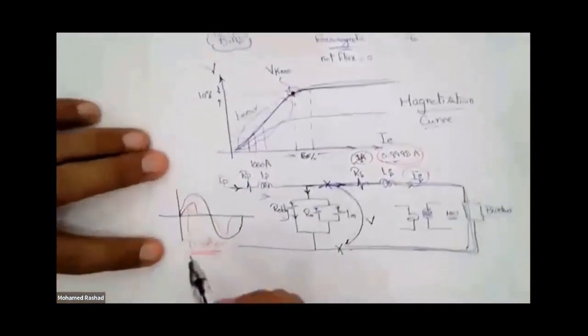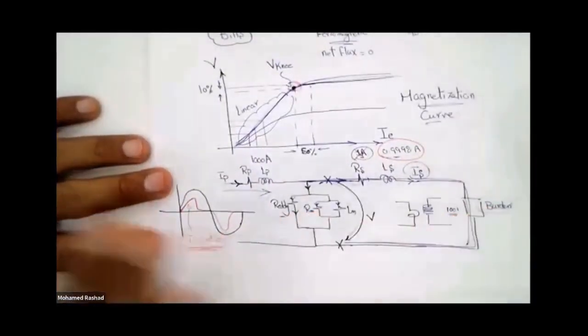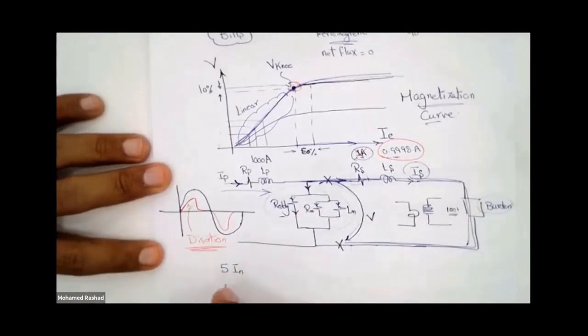What does that mean? Let's say I have a protection device that will operate, for example, at overcurrent at 5 times the current, and at another overcurrent at 10 times the current. I'll give you an example. At 5 times, it is supposed to trip after 3 seconds, and at 10 times, it is supposed to trip after 100 milliseconds, as an example.